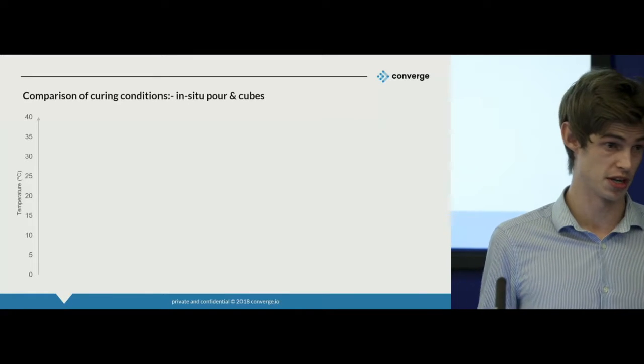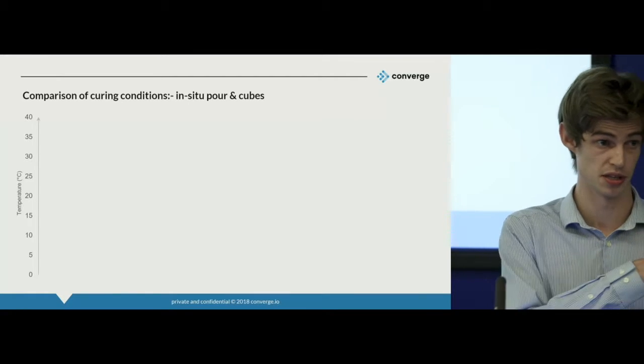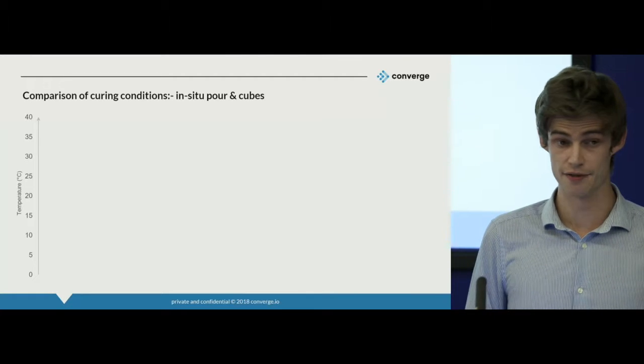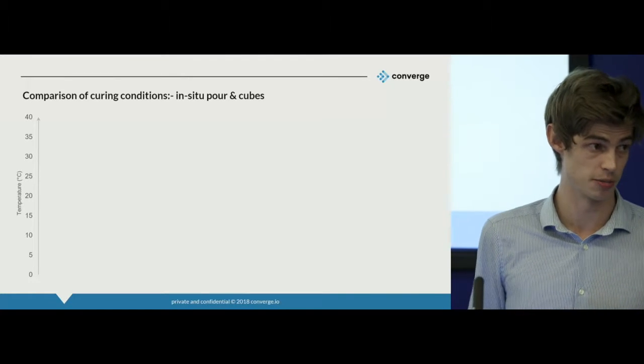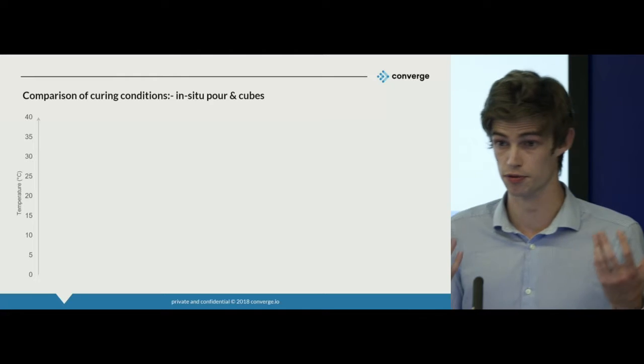What we see quite frequently is concrete being used in high-rise structures, in the slabs, in the cores. And if the concrete is curing slower and therefore developing strength slower, it's going to slow down the overall delivery of the project and hence have late delivery on a project.